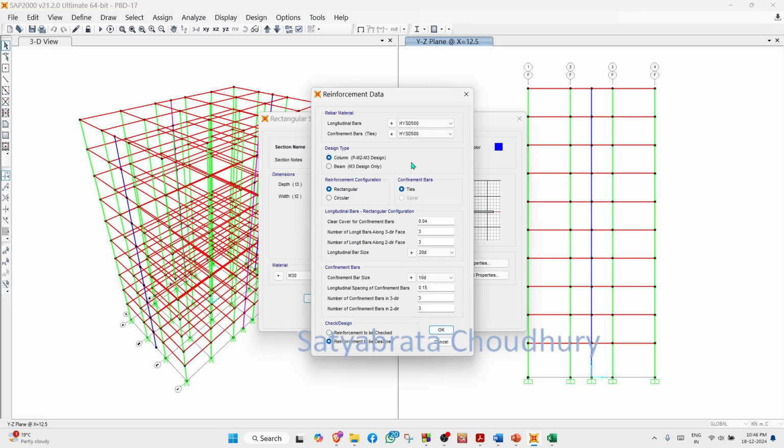So in the column hinges, we shall substitute the shear wall hinges later on. However, the basic model is a wide column system for the shear wall. The other model is what is called the shell element model. And also in some cases like Perform 3D, you can use the wall element directly. In SAP2000 it is not there, but you can use the shell element for the shear wall.